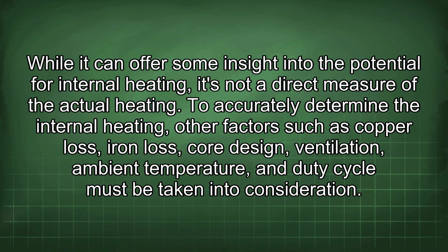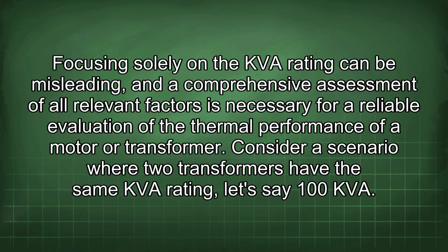In conclusion, the kVA rating of a motor or transformer provides an indication of its apparent power capacity. While it can offer some insight into the potential for internal heating, it's not a direct measure of the actual heating. To accurately determine the internal heating, other factors such as copper loss, iron loss, core design, ventilation, ambient temperature, and duty cycle must be taken into consideration. Focusing solely on the kVA rating can be misleading, and a comprehensive assessment of all relevant factors is necessary for a reliable evaluation of the thermal performance of a motor or transformer.